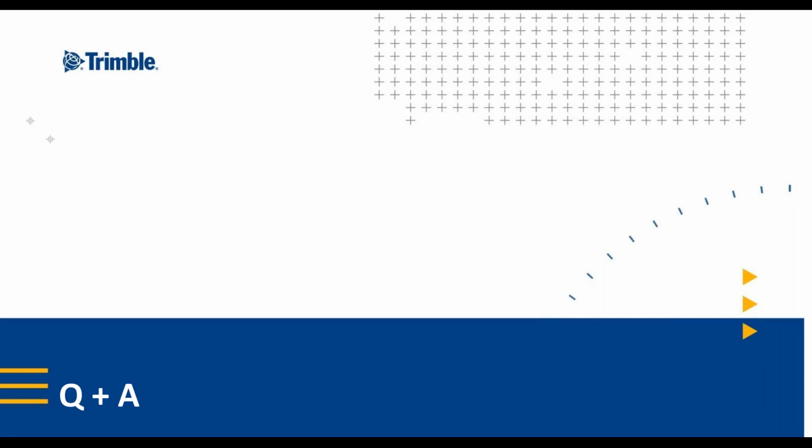TBC would support the requirement, if it is a requirement, to use a 0, 0 project location. You would just type in 0, 0 for your project location, and you can compute your scale factor that way.